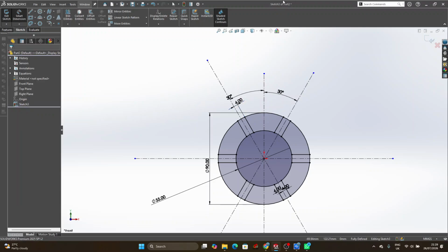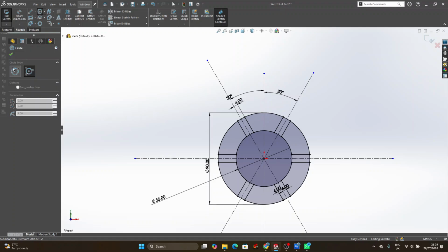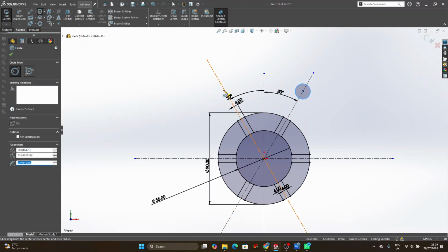So the next step, the two circles that are above it and every other thing that is above, we need to draw it. So go to the circle tool, click on your center circle. As I said, the circle tool that you'll be using mostly is the center circle. The perimeter circle you don't need. I only brushed it to just explain. So I'm drawing this circle here.